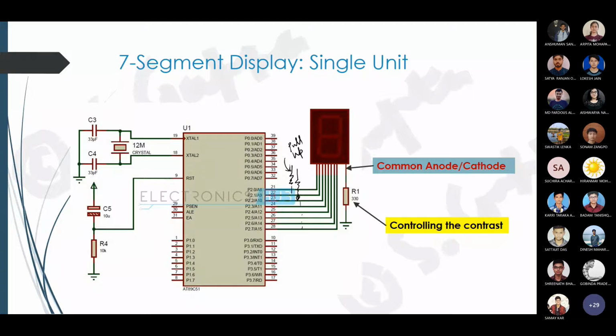So the voltage level should not get down. If this device draws more current or sinking capacity, then the microcontroller must provide it. So the pull-up will be essential for that, right?